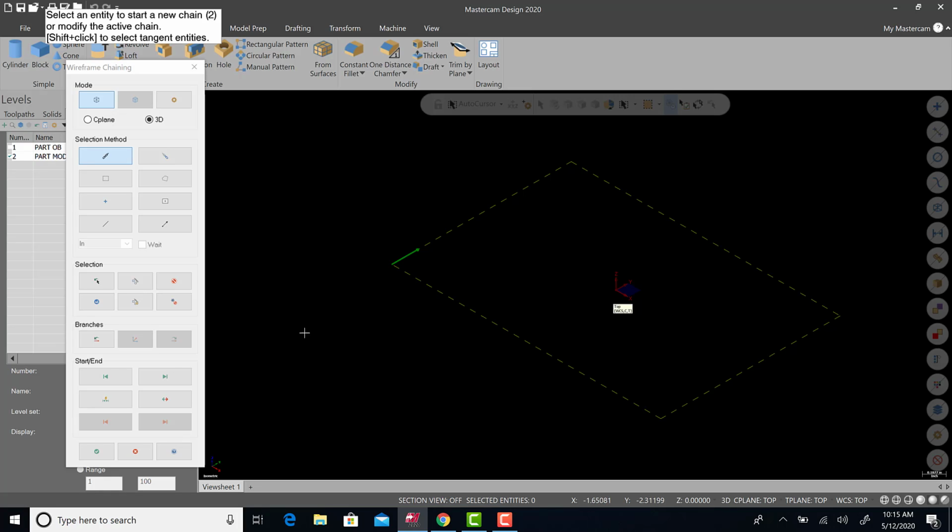Very important. If there's a red arrow, it should not do that right now. A red and green arrow show you the beginning and end of a piece of chain. You don't want that for this. This is not complex enough to have to worry about that or even get into that yet. So hopefully you have one green arrow, and that tells you that this chain is ready to extrude. You should be good to go.